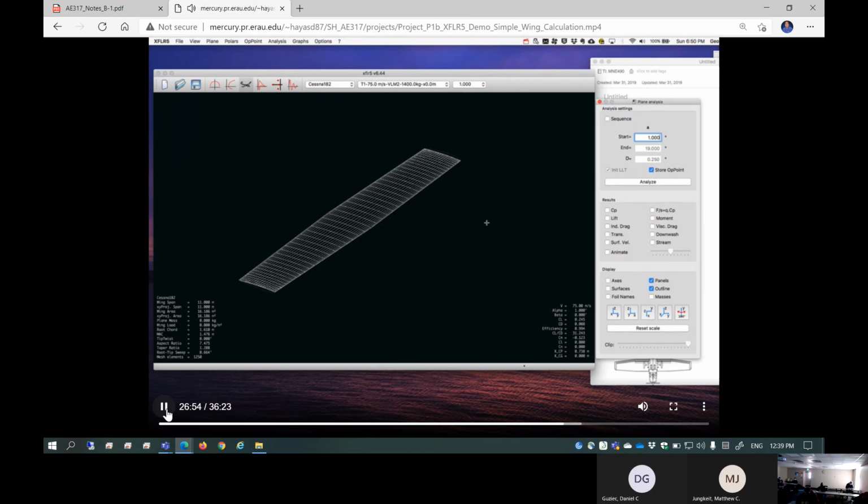It isn't fully coupled, in the sense that, technically speaking, you have a boundary layer here, and once you went to the XFOIL base polar, you could find out the boundary layer thickness, which would change the pressure distribution. We're sort of ignoring that, or we're taking that into account by assuming that the CL that came out of XFOIL already took that into account. So it's this two-step process, and if we had selected Inviscid in the solver, it would have been a one-step process. It wouldn't bother with any of this XFOIL lookup business.